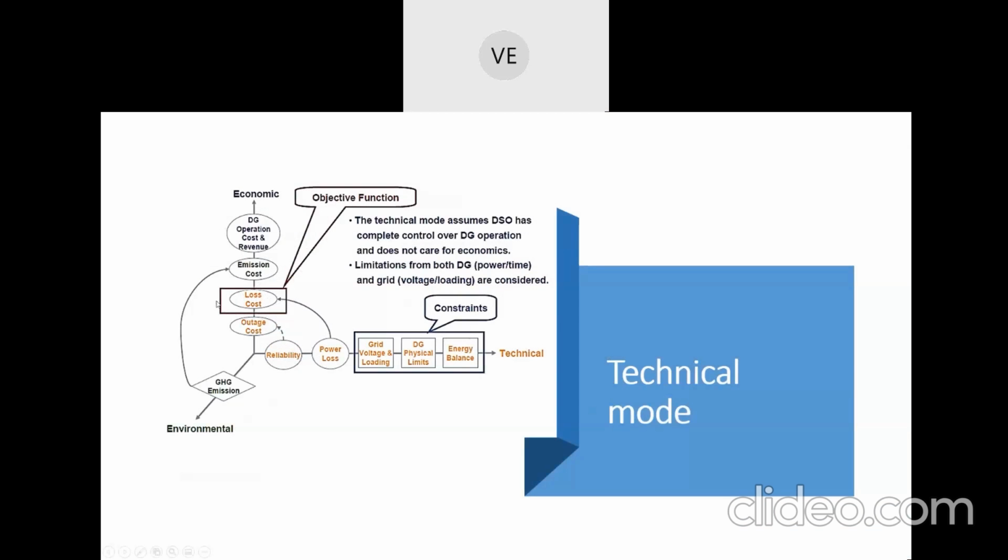So this may completely keep away the V2G activities, because your location in the network has an impact here. If you are farther from the substation, then you can contribute more to voltage regulation services. If you are nearer to the substation, you may not contribute much to the voltage regulation services.